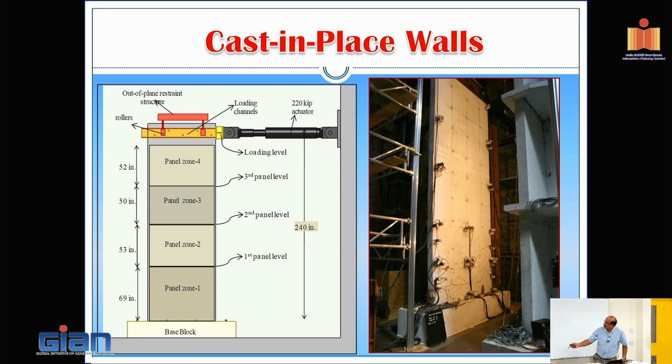So that's the wall. It has a vertical load going through. I think we eliminated the vertical load for the most part. And then mostly our interest was to look at the plasticization and resistance coming from each of the walls. So there was a question about what is the plastic hinge, what does it look like, and how bad this crack gets. Getting all interesting now. The questions are very, very detailed.